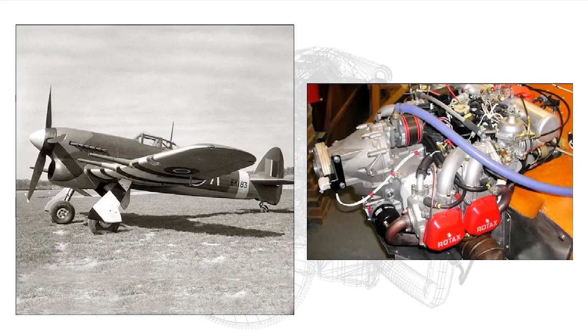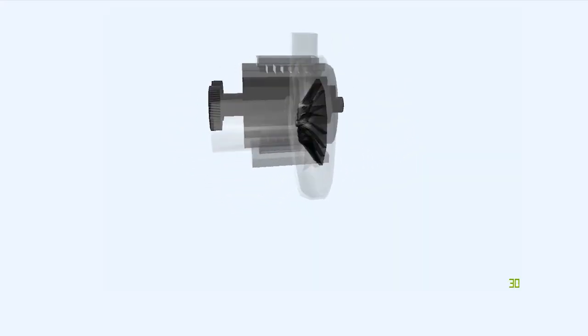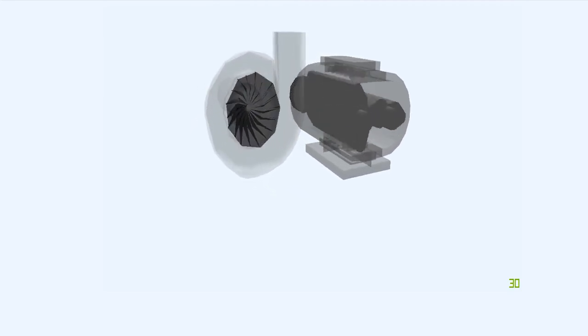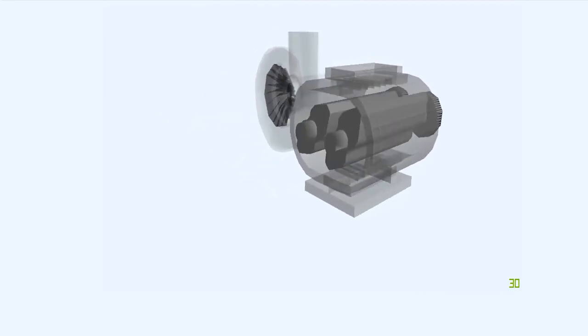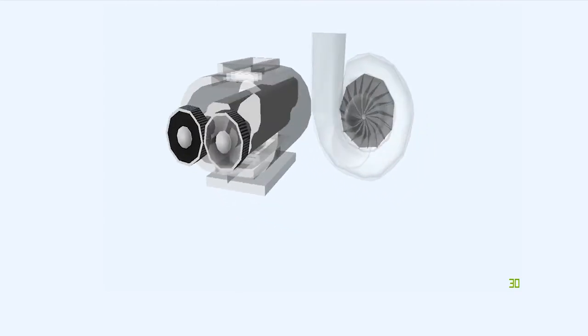Superchargers capable of maintaining sea-level values of power up to high altitude require a control system to prevent excessive pressure being generated within the engine at low altitude. Engines with this type of control system, similar to the one shown here, are fitted with altitude-boosted superchargers. Both the Roots-type compressor and centrifugal compressors are used as superchargers on aircraft engines, although the centrifugal compressor, because of its relative simplicity and ease of manufacture, is more commonly used.